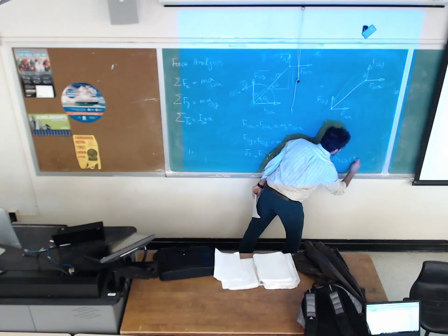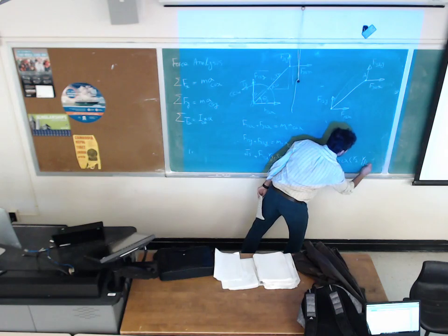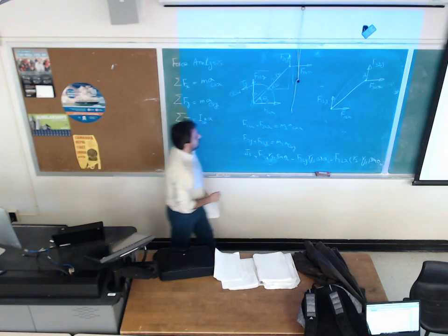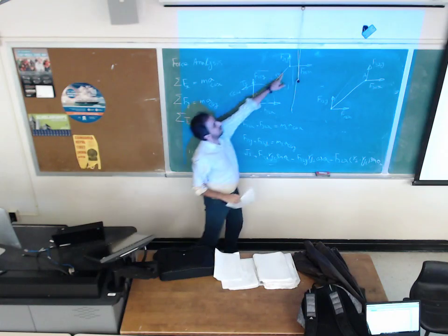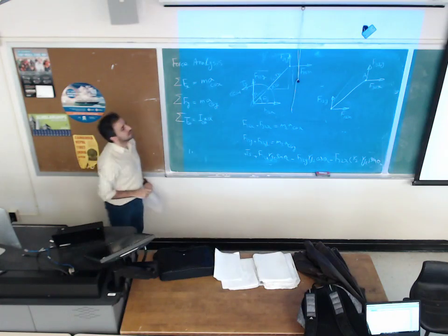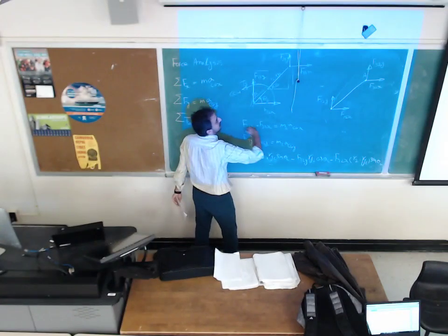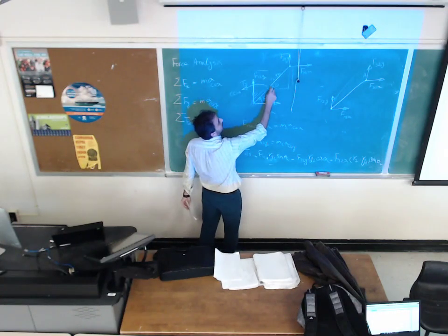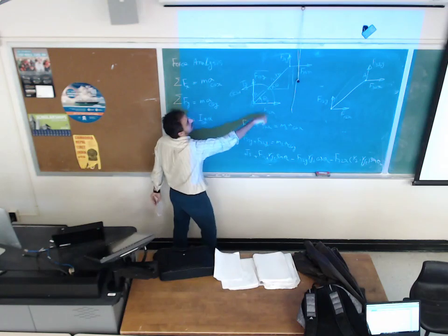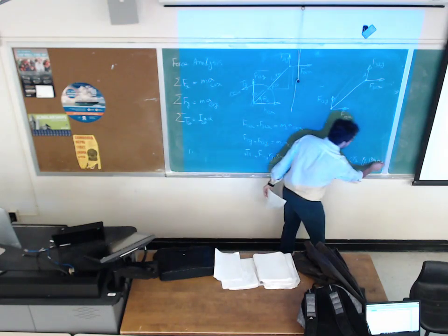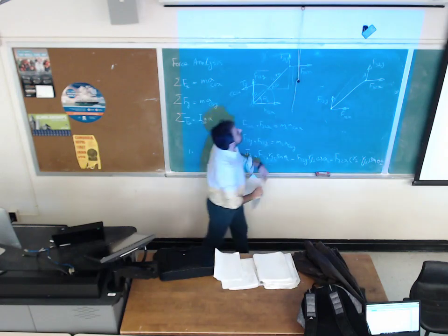And the last term for the moment is coming from this force. The force is making counterclockwise rotation about the center of gravity in this direction, so I put positive. How much would be the moment? Force times this distance. This distance is R2 minus RG2 cosine of theta 2.